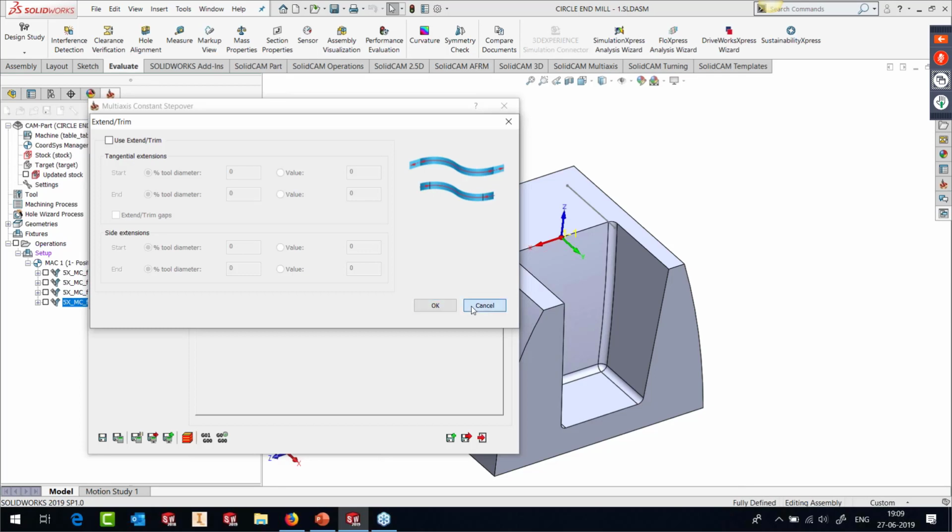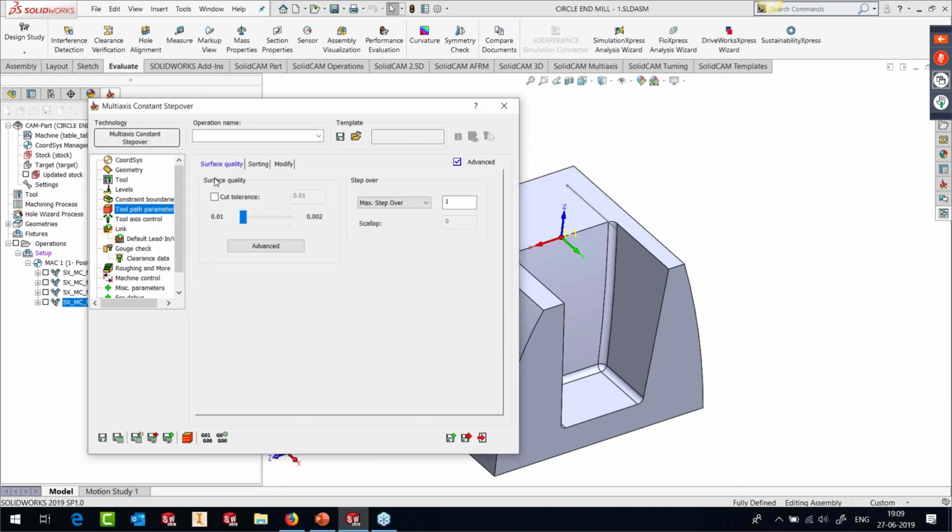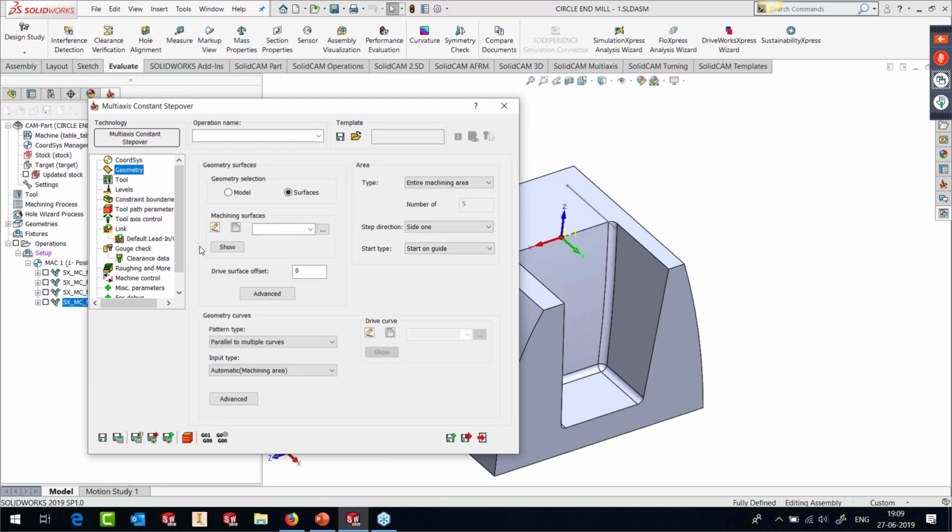But the whole thing is here that you cannot use a closed mesh to extend the toolpath. Your geometry has to be a group of several surfaces. It could be thousands of surfaces. You can select using color or any other method. And once you select these group of surfaces, create an open mesh, and there the toolpath can be automatically extended by any value that you want.